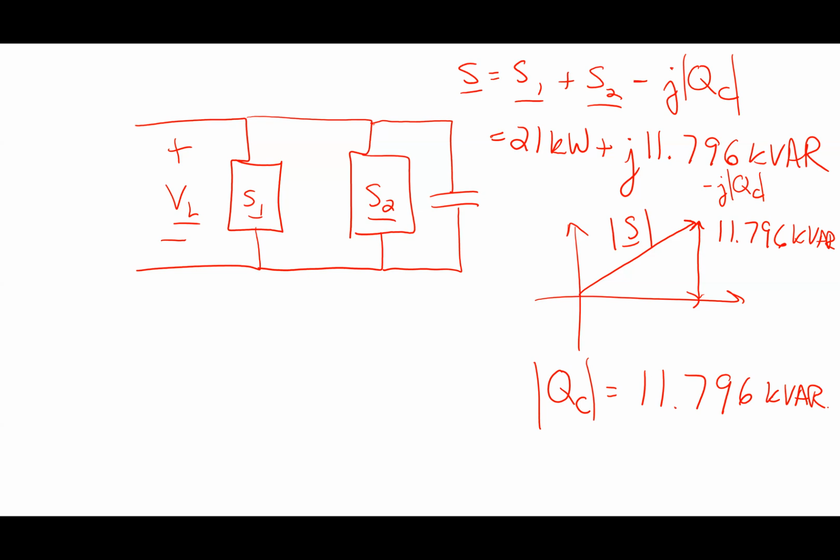Basically, I'm going to talk more about this later. What we're saying is right now that Q that those two loads need is being supplied by Duke Energy. Some generator somewhere is producing current that's going out onto the grid to supply the Q. If I need a positive Q in these loads, I could supply that Q locally by a capacitor bank.